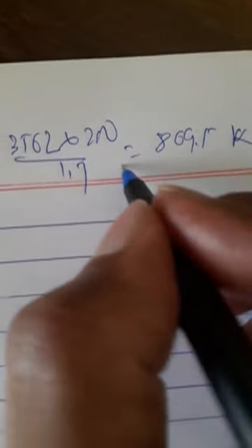Now third step, strength calculations. First is yield strength, Tdg is equal to Ag fy by gamma m0. So Ag provided is 3562, fy 250 divided by 1.1. So you have 809.5 into 10 raised to 3 newtons, or 809.5 kilonewtons, and this is greater than 600 kilonewtons. Hence okay. Second, rupture strength.